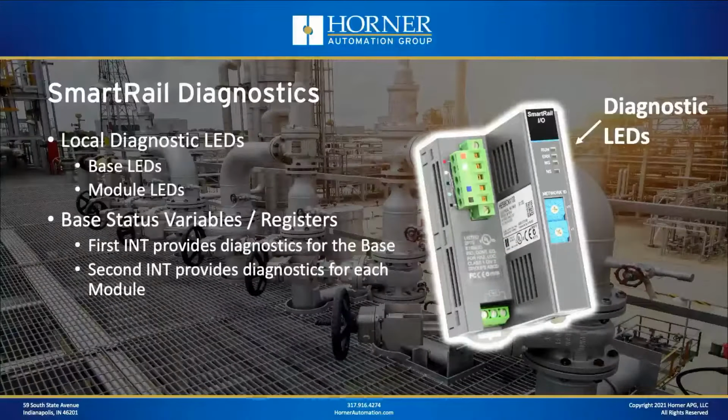All right, next we're going to dive into diagnostics because CsCAN SmartRail has some pretty good diagnostics. So first of all, let's take a look at the diagnostics available from the base. You have two levels of diagnostics. You have LEDs available on the front, and then you also have the status registers or status variables that I just configured in CsCAPE that you can reference from the OCS side of things, where the first word of that status variable gives you diagnostic information for the base. The second word of the status variable provides you with diagnostics for each module that's connected to that base.